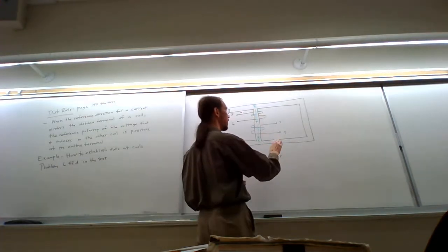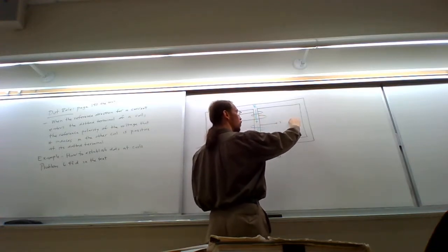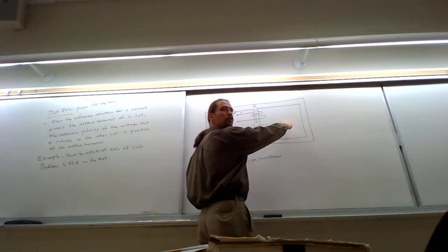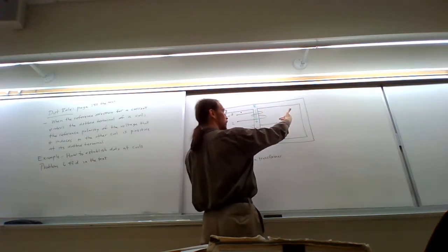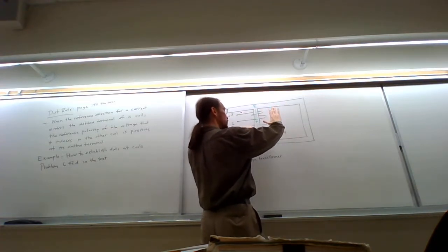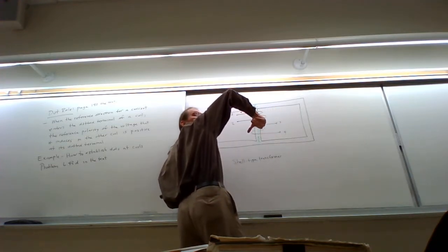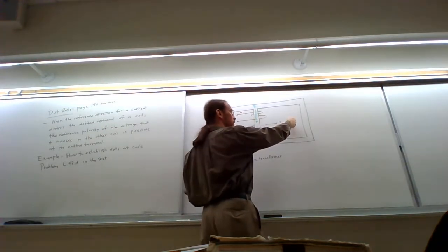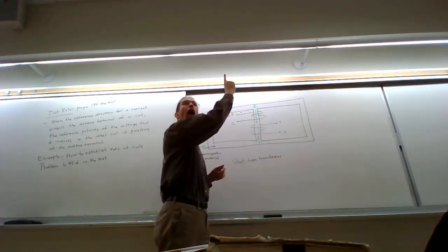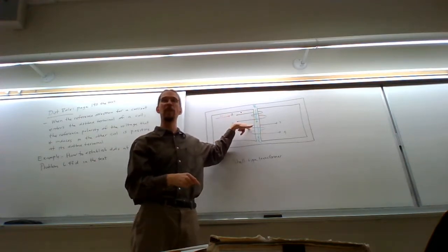So here we have literally two possibilities. Suppose that I actually fed in a current going into terminal 3, right? Now, according to my right-hand rule, if it's going in and I'm interested in the inside of this, notice that I would have to turn all the way around, right? And that magnetic field generated by this current entering into terminal 3 would go upwards. Notice that that is subtracting away from the magnetic field that was there already.